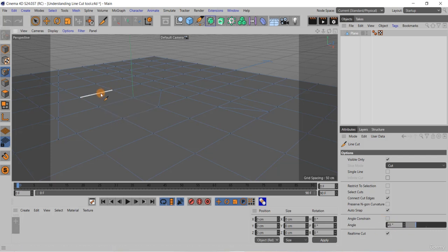Now one more thing I would like to mention here is that suppose I am making one cut over here, I have clicked over here and I am clicking again over here. I can even make a point on the line just created like this, and if I am pressing shift while clicking on this line, I can move this point like this, meaning wherever I want I can click at a point like this. I can just move the point, and if I press control, then that point can be removed. So like this you can make the cuts as required. Again I am pressing the escape key.